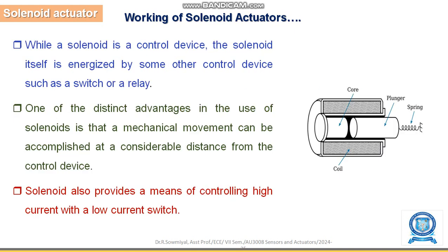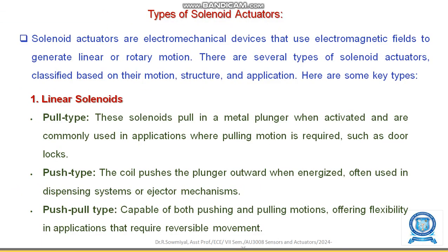While a solenoid is a control device, the solenoid itself is energized by some other control device such as a switch or a relay. One of the distinct advantages in the use of solenoid is that a mechanical movement can be accomplished at a considerable distance from the control device. Solenoids also provide a means of controlling high current with a low current switch.